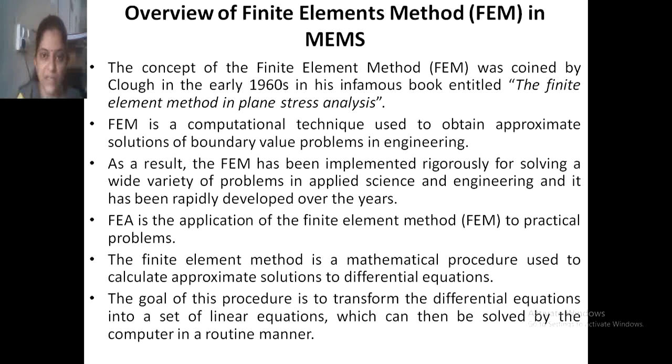Early in the 1960s, the finite element method in plane stress analysis was introduced in a famous book. FEM is nothing but a technique used to obtain approximate solutions of boundary value problems. The procedure is to transform the differential equation into a set of linear equations, which can then be solved by the computer in a routine manner.